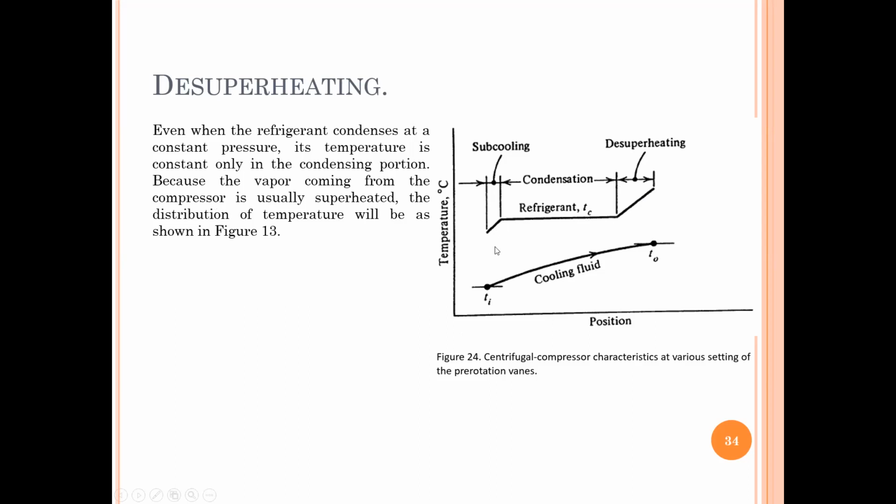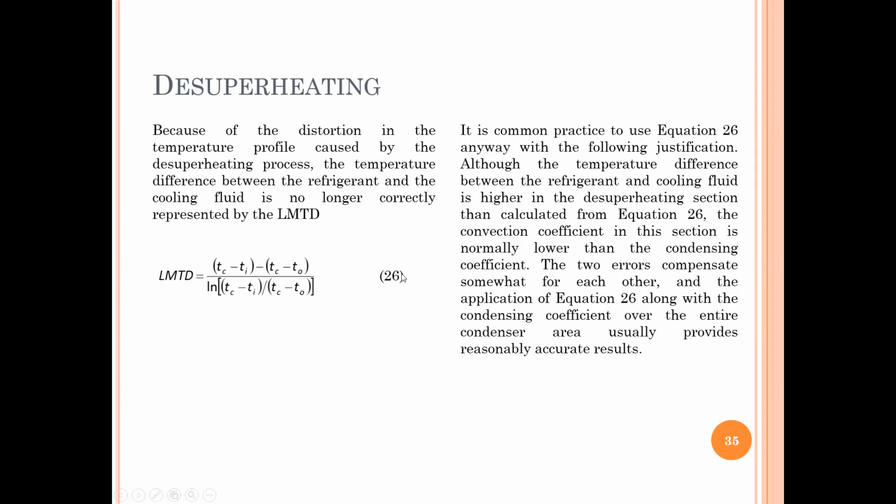So, anong purpose to ba't ina-explain? Andito. Because of the distortion in the temperature profile caused by the desuperheating process, the temperature difference between the refrigerant and the cooling fluid is no longer correctly represented by LMTD. LMTD is equal to (t_c minus t_i) minus (t_c minus t_o) over ln of (t_c minus t_i) over (t_c minus t_o). Yung mga temp saturation to.